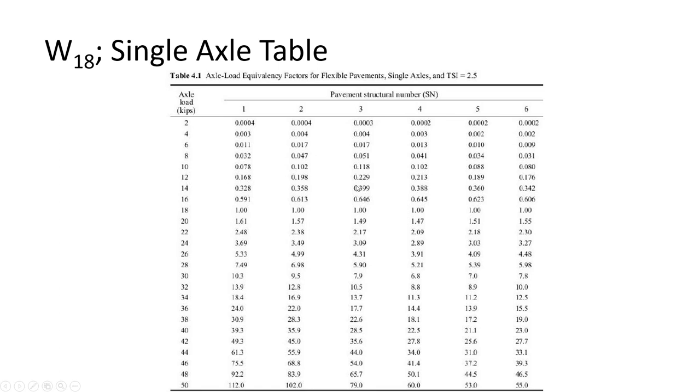So this axle load, it's only 12,000 pounds. 18, right, is 1. Look at that. Oh, there it is. So an 18,000 pound single axle is 1.0. That's the definition of the whole thing, right? But if you have less or if you have more than 18,000 pounds, these are the factors that you've got. And you can look at how, as weight increases, the ESALs increase.